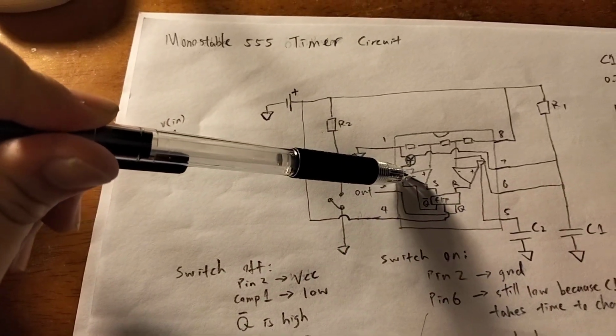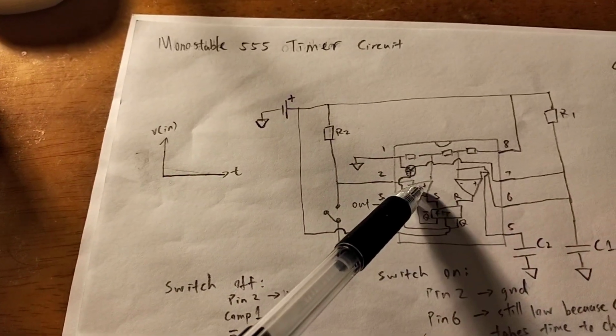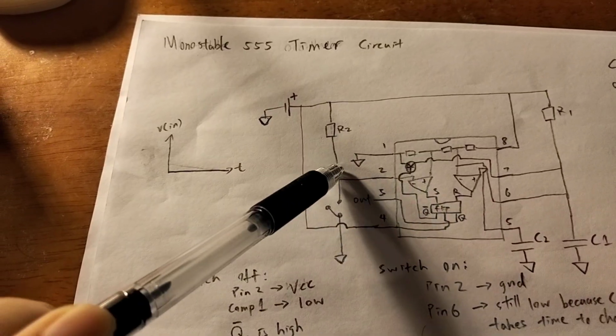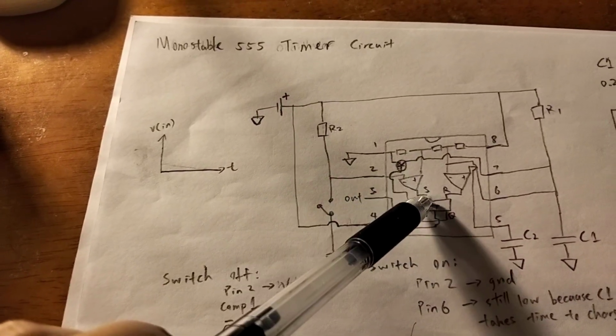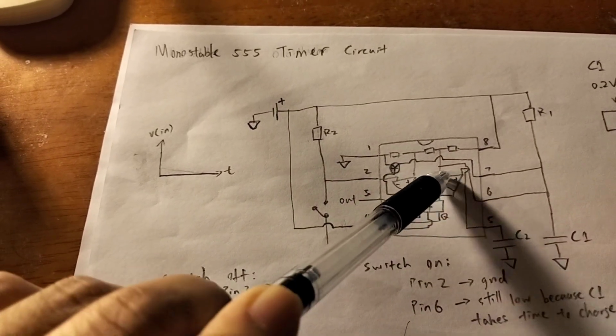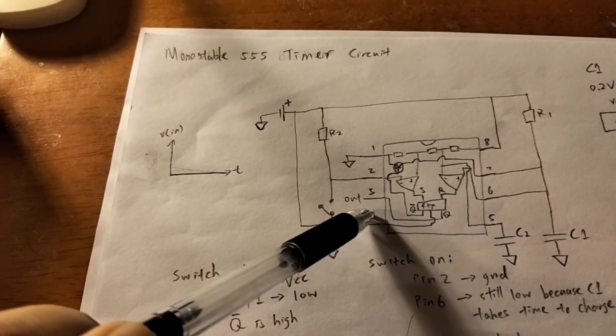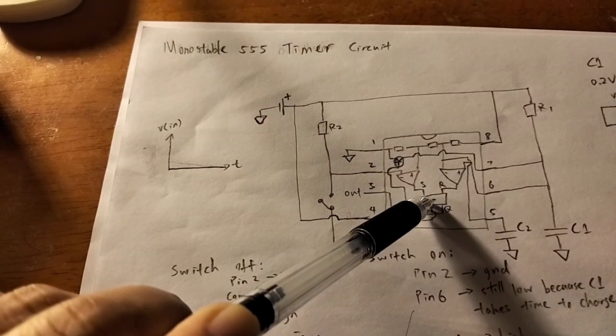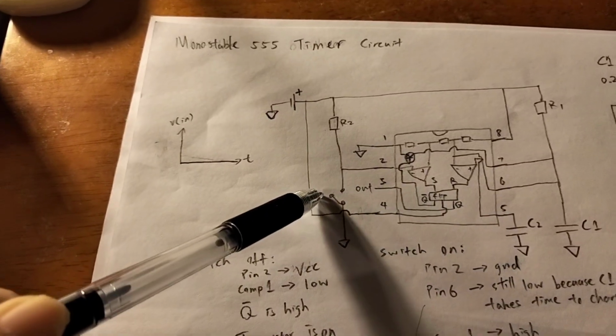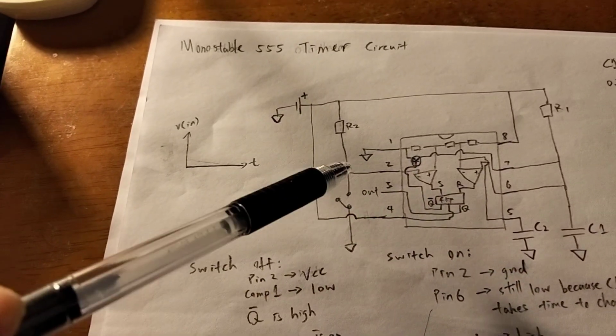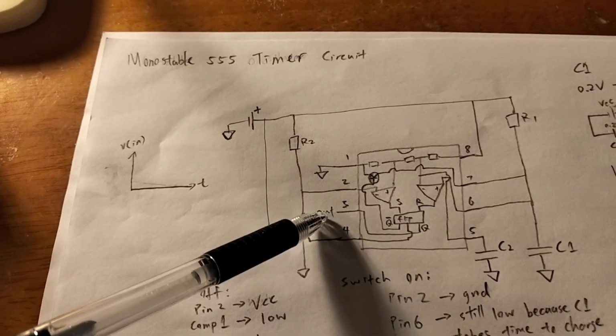And then when you let go of the switch, this comparator straight away drops low. And therefore it resets straight away, because this is already high. We already finished the timer, and so the flip-flop immediately turns low when you let go. And that's the behavior that you see, as expected.